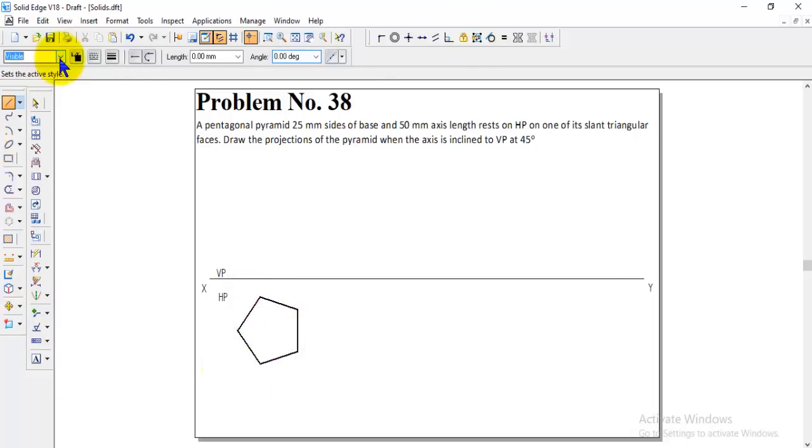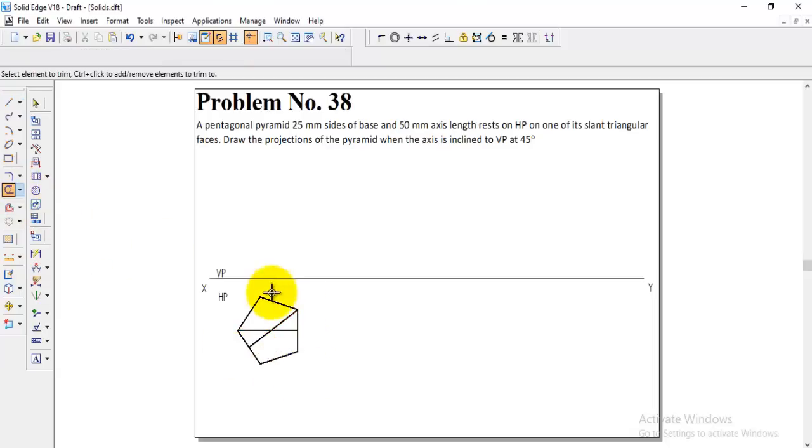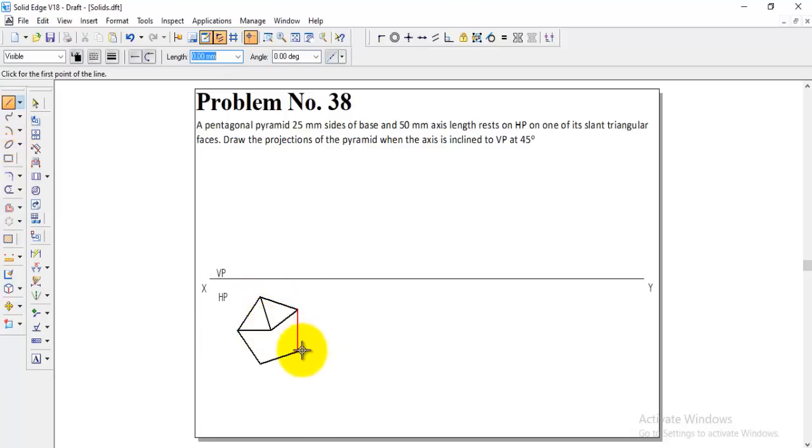And after that, when the pyramid comes we need to draw the center lines. Go to the visible line to the center. From all the corners we have to make a visible line. That is the most important thing we have to do here. How to get the center: draw any two bisectors, and we will get the center. Take the corner to the opposite edge midpoint, draw the lines, and this extra you can trim. And then for the remaining corners also you have to draw the line to the center with the visible line.